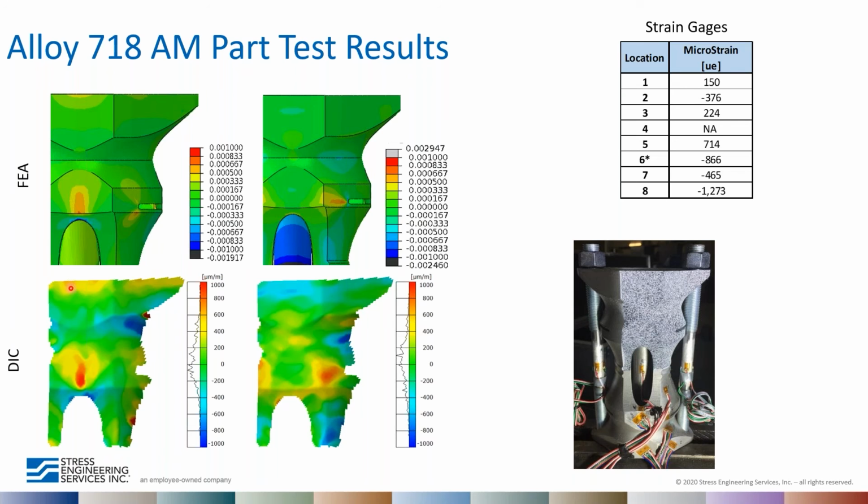It looks like maybe the boundary conditions are in the right spot and being applied correctly, because the contours are similar, but maybe they're just not magnified enough. Maybe the material representation in the model is not accurately representative of what this additive material really responds like.